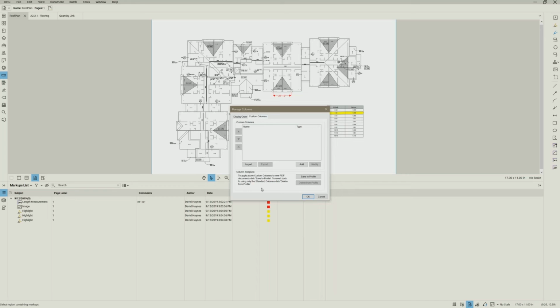And now I want to add a custom column because I want to do a roofing takeoff of this plan, and it's flat. If I just did straight areas, I would not have enough roofing material. So I use this as an example. You could use any methodology where a calculation is used. In estimating, we often use calculations to take care of waste factors or other ways of taking flat 2D and making it real-life 3D. That's why the roofing one is a good example.